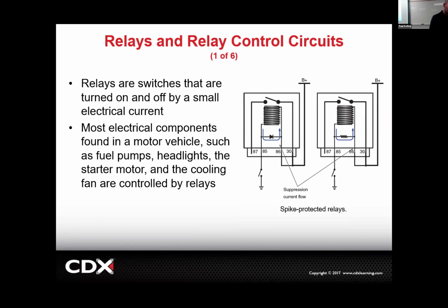Relays, we talked about. So if we tie what we learned earlier, I want you to notice this is the coil of the relay. This is what we consider the control side, right? So 85 and 86. Now, I'm okay if you don't want to memorize these numbers. I actually don't really memorize these numbers. For whatever reason, on the domestics, these numbers were consistent all the time. So it was helpful for some technicians to know the numbers. That way, when you went to diagnose the system, you could really quickly know, like, am I testing 85 or 86? 85 and 86 is the control side.